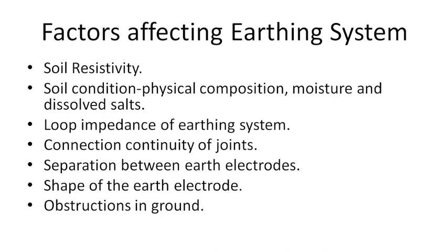Normal case, the electrodes are not supposed to be placed very near to each other. Why? Because when a short circuit fault, a severe current fault happens, normally it would be dissipated to the earth. When it is dissipated to the earth to an electrode, the current will have a spherical locus. The current distribution will have a spherical locus.